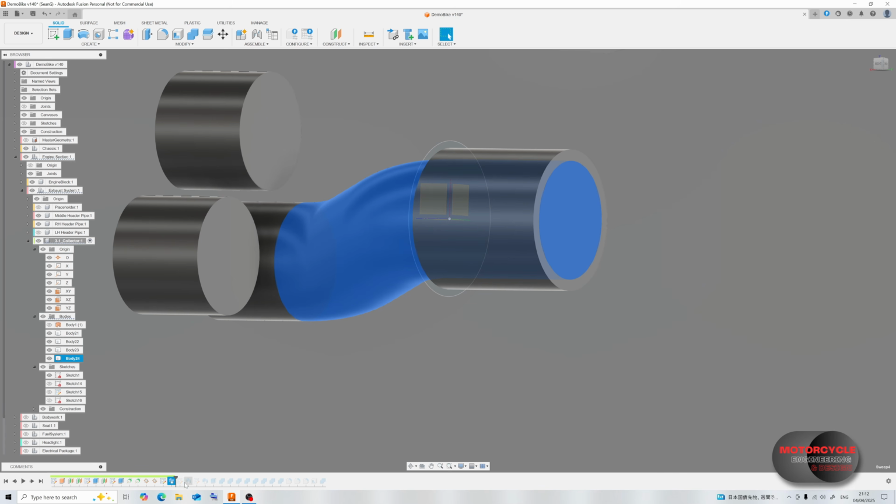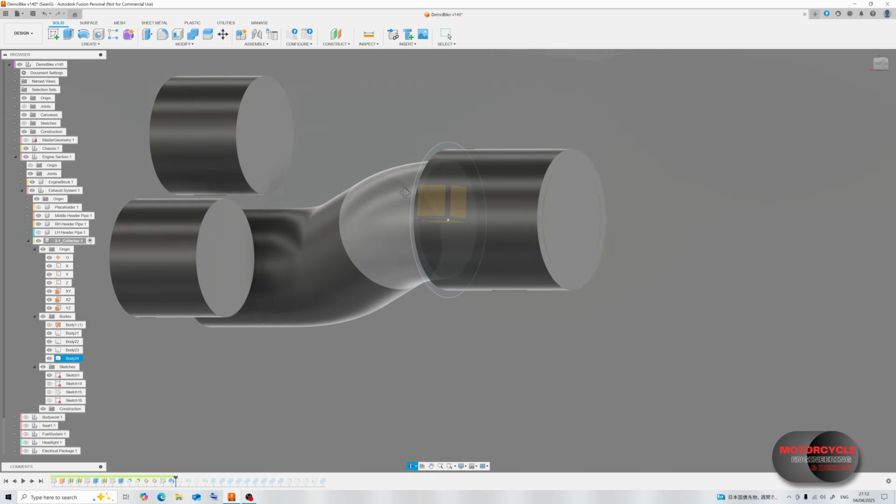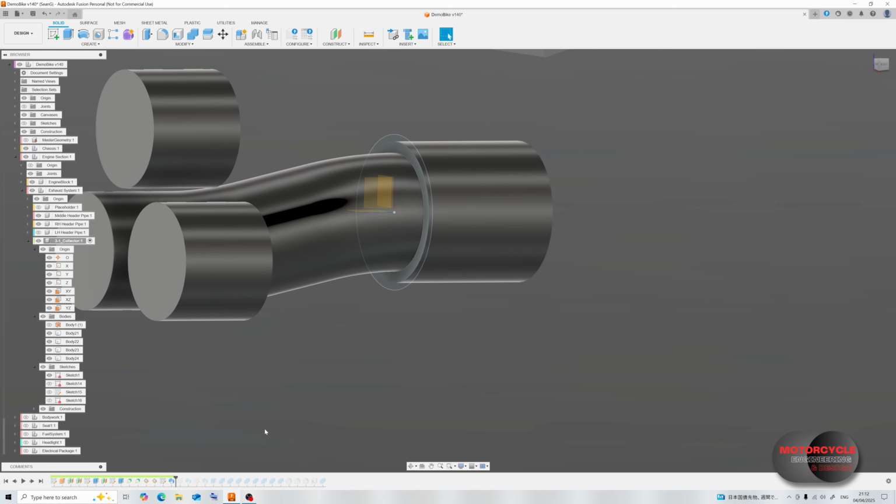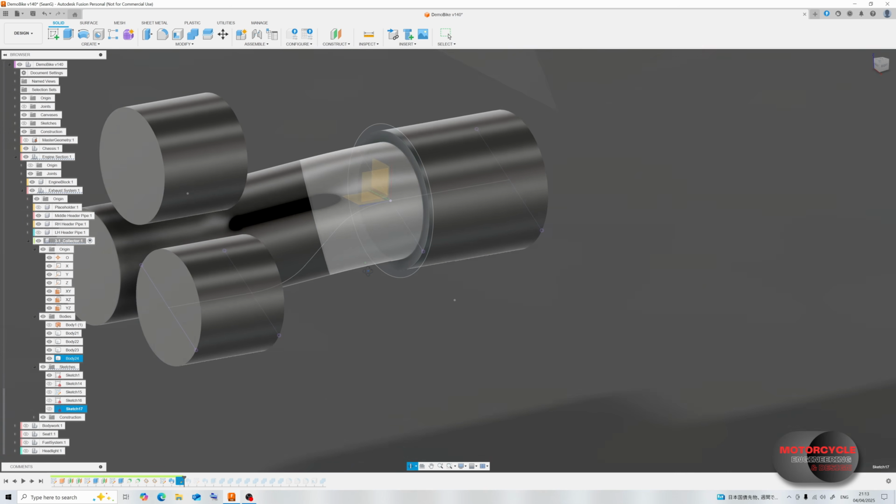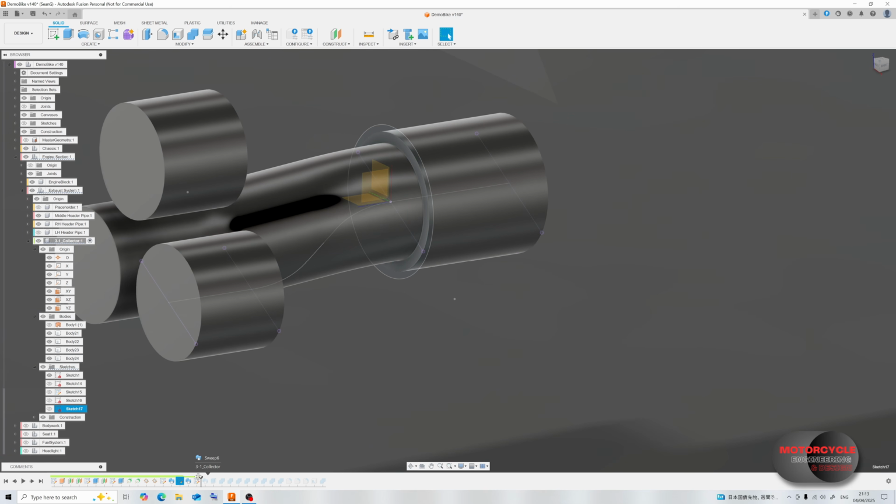From that sketch, we then just sweep the profile back to the initial tube. You can see the initial tube is oversized currently. That's because I plan to extend and draft or taper the extended tube into these 3 tubes that are combining together. From there, we have another sketch. Basically, we're going to repeat this for each one.